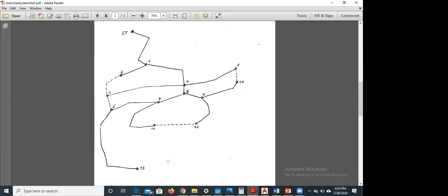Assume 50. Safety factor is still 2. Number of occupants per building is 50. The water demand per person is still 100. Use the same parameters we used in our design. The only difference is that the land use says high density, meaning there are 50 persons per house. That means you must build at least a four-story building per plot in that area.